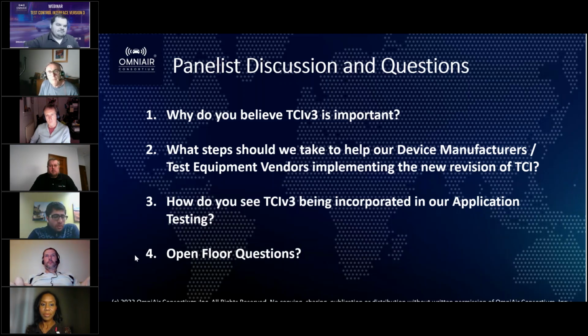It's basically to test congestion. There's a section in J2735 where the applications are supposed to react to a bunch of BSMs from different devices in a small area. So that is what congestion mitigation is. If the devices are equipped to handle it, you can use TCI to enable or disable that functionality on the device, and then study the response of the device. It's part of SAE J2735. It comes from there. Thanks, Abhishek.